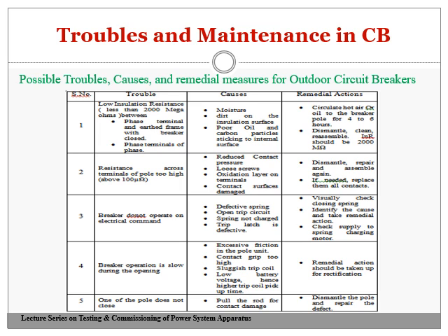That's why the insulation resistance becomes low. So the first trouble is due to absorption of moisture content by insulation and poor oil quality, which also gives a possibility of low insulation resistance.